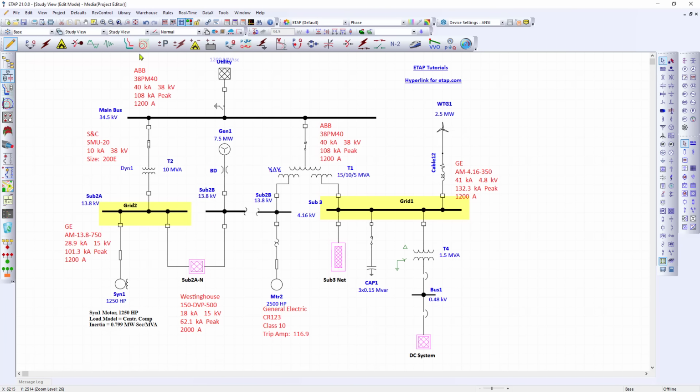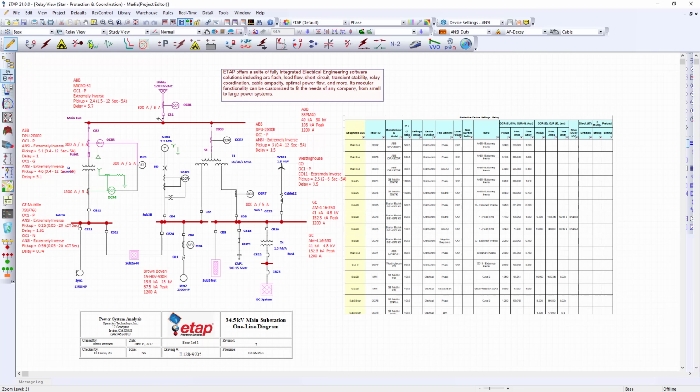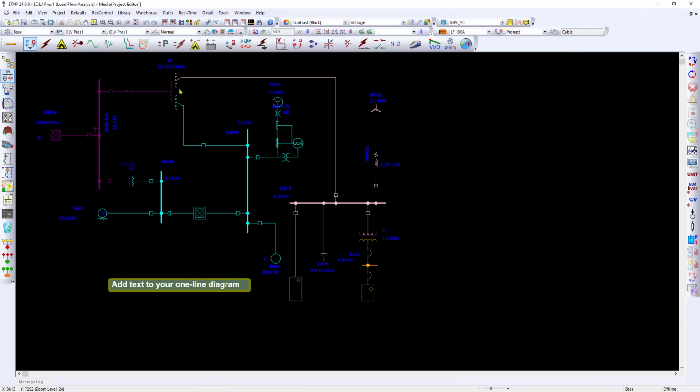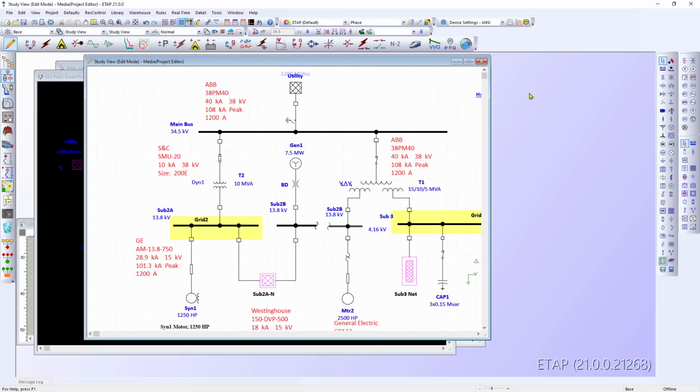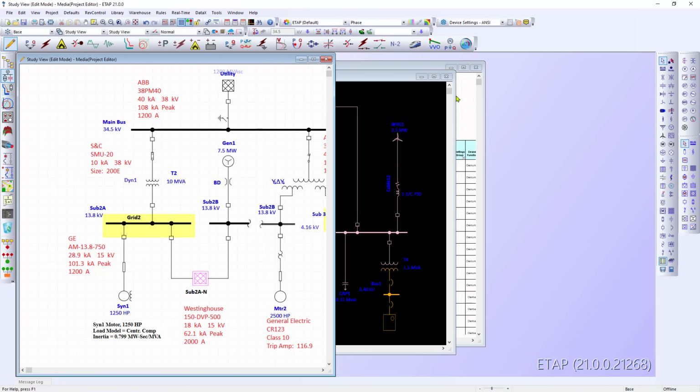And then if I have multiple presentations, so within ETAP, I can have different presentations, as we talked about when we talked about the multidimensional database. I have a relay view here where my relays are shown. Originally they were hidden. And then I have another presentation that color codes by voltage on a black background. And if I'm using these for different purposes, I can simply use Control and an arrow to dock them.